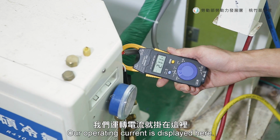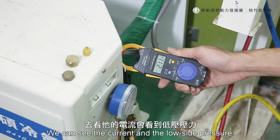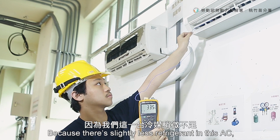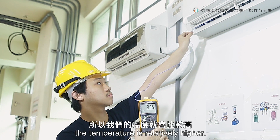Our operating current is displayed here. There's a clamp ammeter. We can see the current and low side pressure. Now we'll use a thermometer to measure the temperature at the supply vent. Because there's slightly less refrigerant in this AC, the temperature is relatively higher.